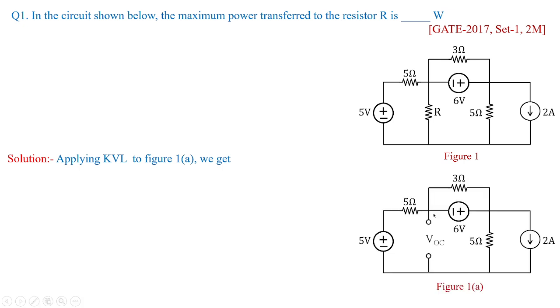So you can see here I'm taking out this resistor, and I'm trying to find out the voltage across this terminal, because I need to obtain the terminals' equivalent network along with the load R here. So for that, we have removed this resistance from these particular terminals. When you apply KVL, you're going to get the currents flowing in the given loops. So current 1 and current 2 would be, clockwise, assuming both the currents are flowing in this fashion.